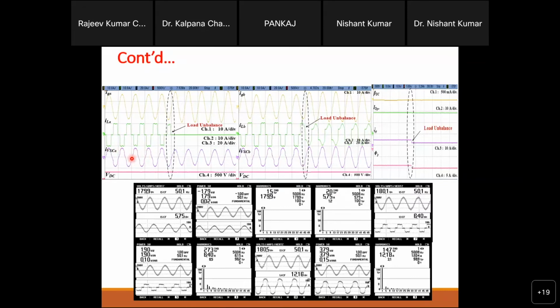Because our converter is not only generating active power for the grid. Our converter is also generating the load current, and the rest is pure sinusoidal for the grid. This is the combination of both, which is why it is not pure sinusoidal, this is the VSC. The VSC is generating the nonlinear current also according to the requirement.